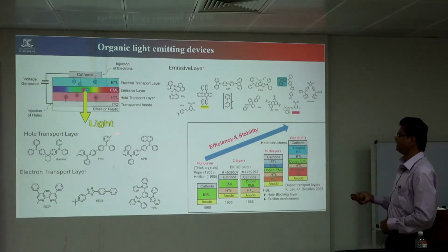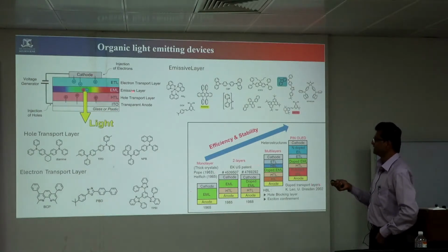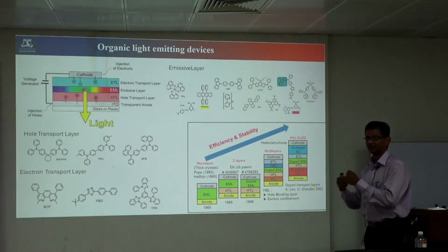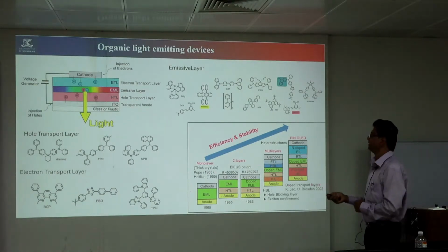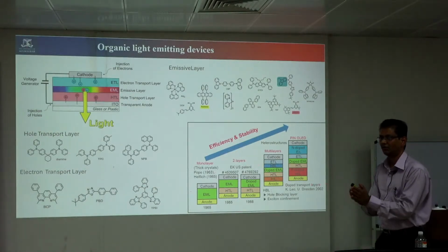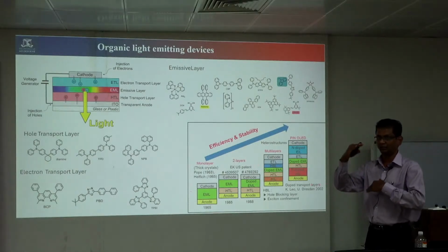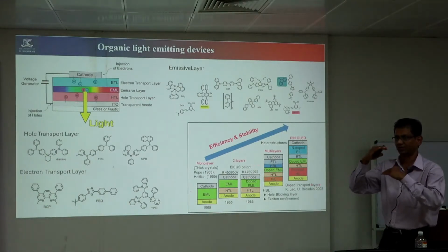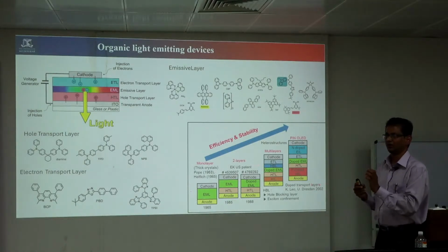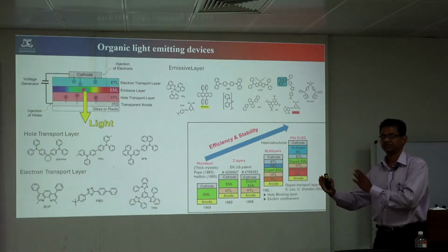Okay, in LED we use both the hole transport layer and the electron transport layer. The emissive layer is the photoactive layer, where we generate electrons and holes that recombine and generate the light. Like what we have seen in the organic photovoltaic, here also we have 5 layers: cathode, anode, hole transport layer, electron transport layer, then the middle emissive layer. All 5 layers is the basic one. We are also going to see multilayer devices, because of fine-tuning the efficiency of this cell.